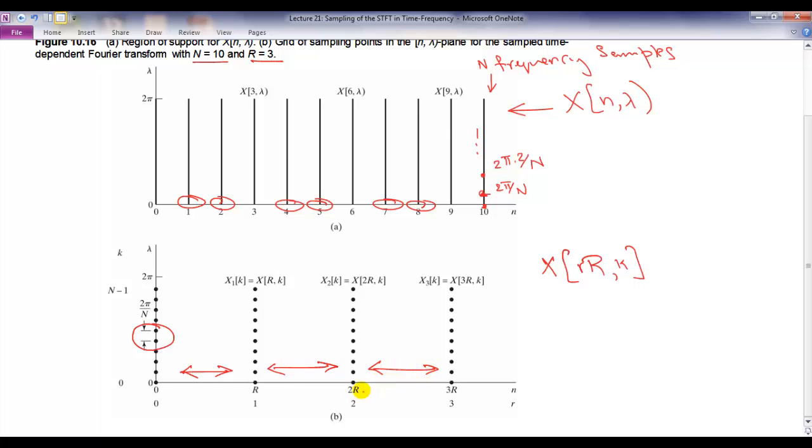And this smaller version of the short time Fourier transform is enough for you to reconstruct the original sequence. Of course, if you are visualizing it, you will lose some information in your visualization, and that depends upon how much you are willing to subsample in the time domain.